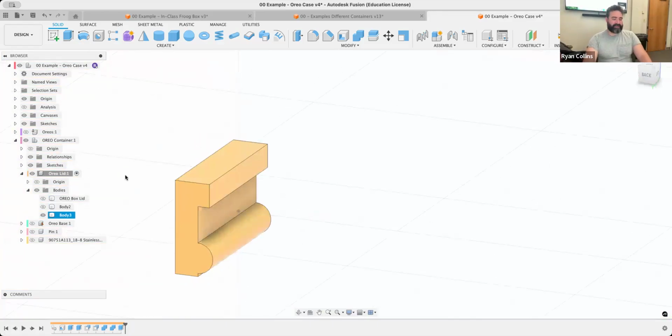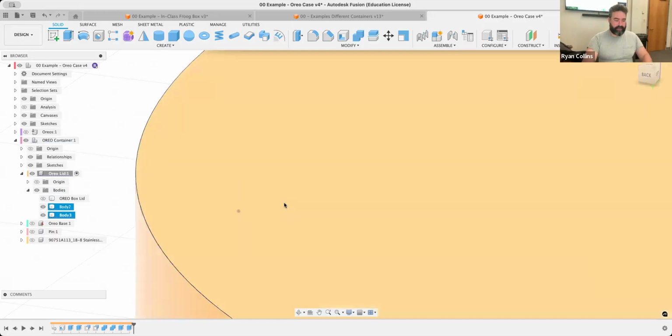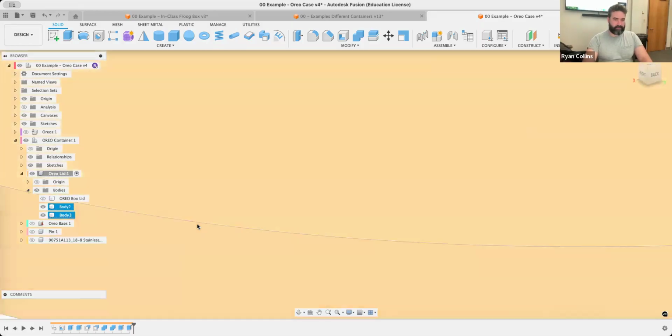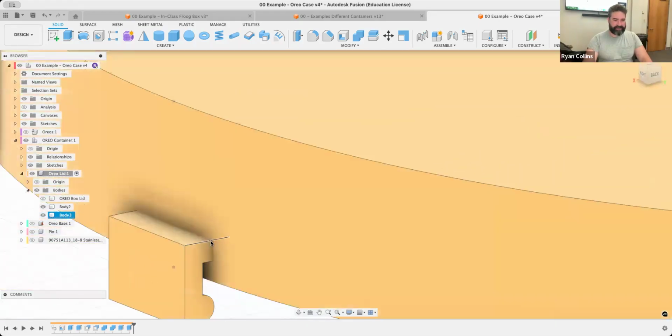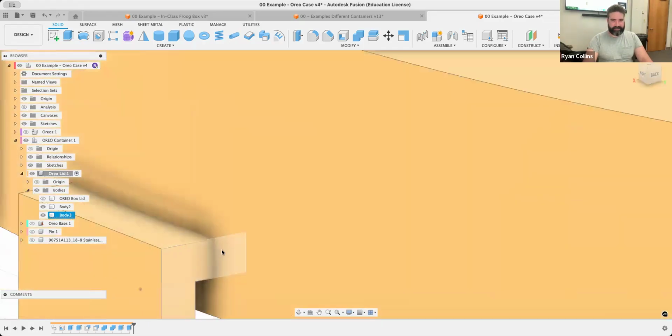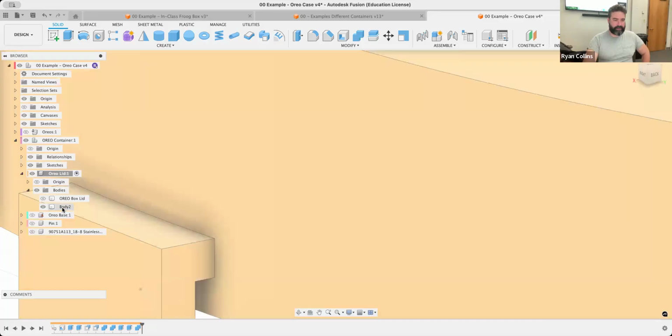This is all just because I'm running into this additional issue because I'm trying to make a flat thing on a round thing. That's all. All right, so I deleted that last extrude because that was where the problem was. I just need to select this face and drag it in, like one was too much, so 0.5. Okay. There we go. So now I just got this little notch. The problem was that curve wasn't extending properly. So now I'm going to join that whole thing together. So that one to that one body, good.